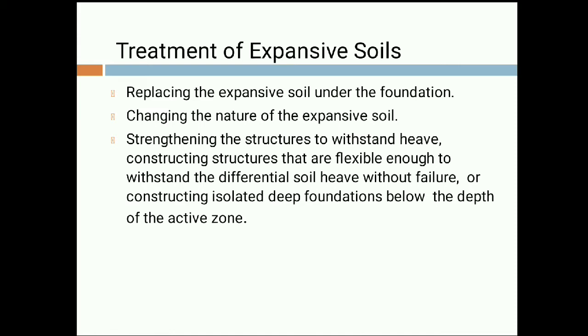Third one is strengthening the structure to withstand heave, constructing structures that are flexible enough to withstand the differential soil heave without much failure, or constructing isolated deep foundations below the depth of the active zone. Active zone is basically the depth up to which there is more moisture variation, and there will be frequent change of shrinkage and swelling of the soil.